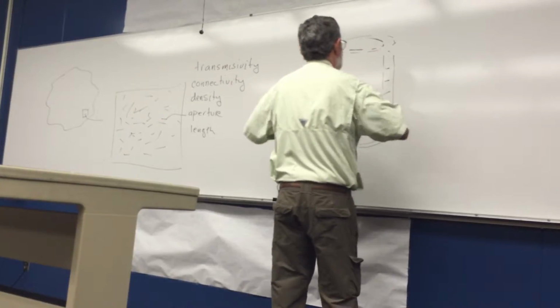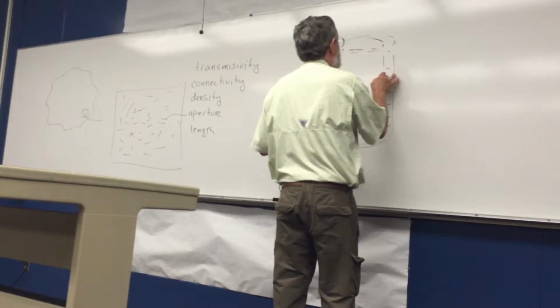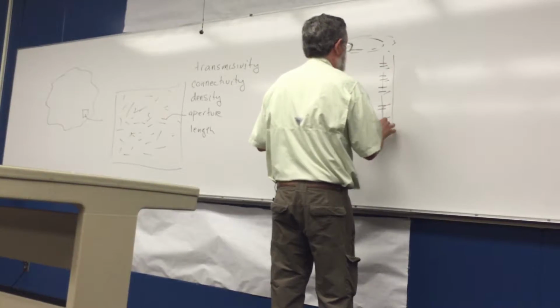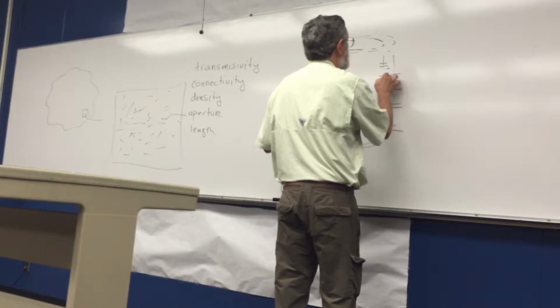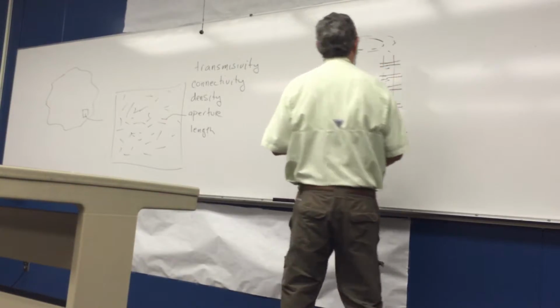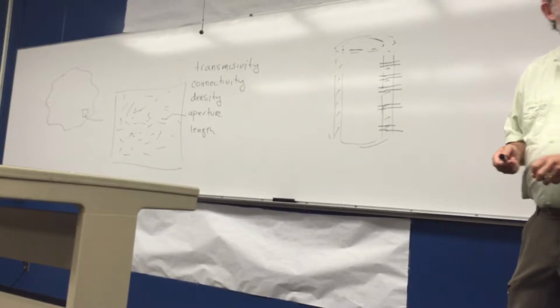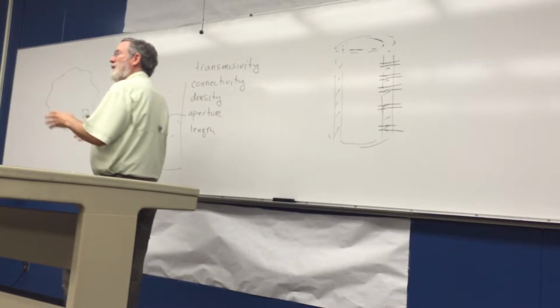So then we set in a shape charge, and effectively you blast a series of holes into the casing that reaches through. These holes will penetrate out into the formation. And you choose how many shots you're going to have. Is this 10 shots? Is this 20 shots?